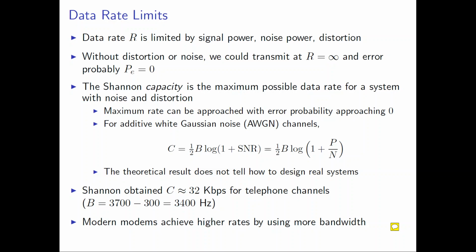when you don't have wireless fading. Think of it like communication over wires, or communication between a satellite and the ground station, satellite and TV. In this case, you only have the additive white Gaussian noise effect. So what's the channel capacity for this system? It is half of the bandwidth multiplied by log 1 plus the signal to noise ratio.